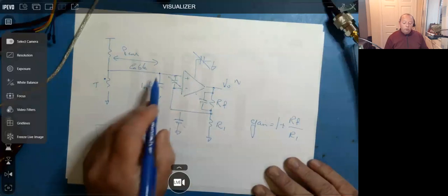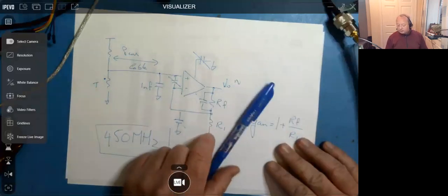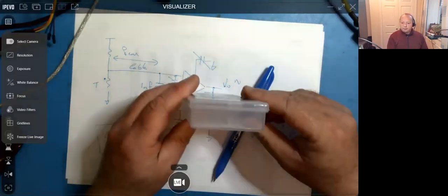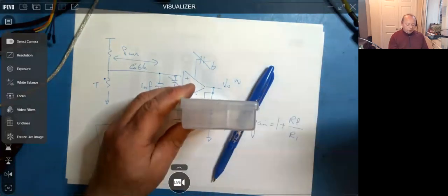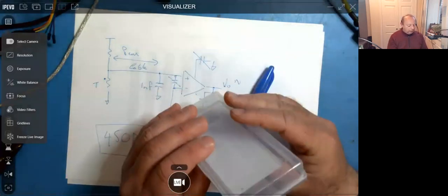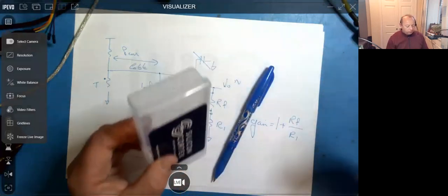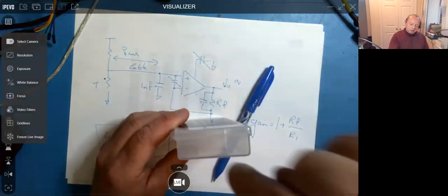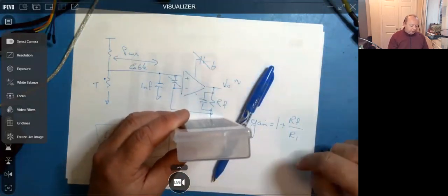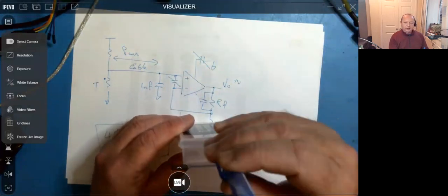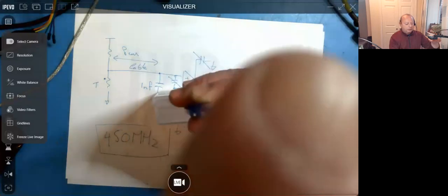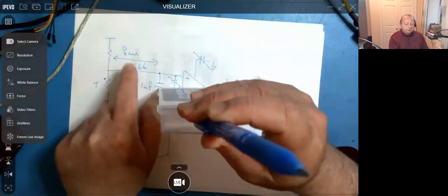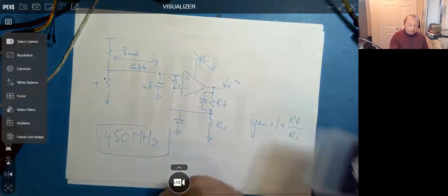So also we found, I'm going to simulate it here, depending on what orientation the product was in, because when you do EMC, you test it from different angles. Every cube's got 6 sides, and you actually test it on 4 of the 6. Don't ask me why it's not all 6. And we found from one particular direction it was causing us a problem. And anything in line with the antenna, which is the camera, which is you, is probably then going to be the route in. And yeah, this cable. And we'll talk about more of this in our next, we'll talk about approval.